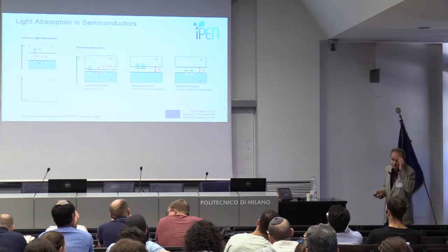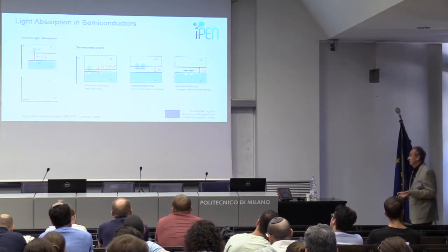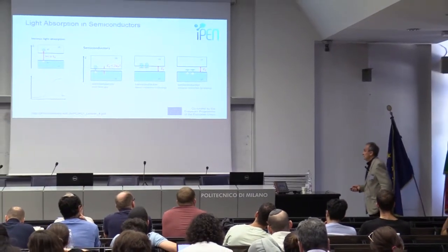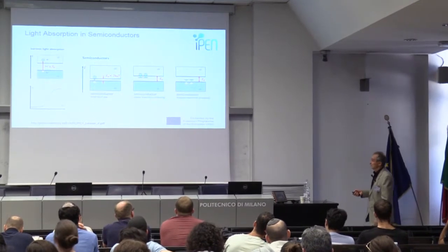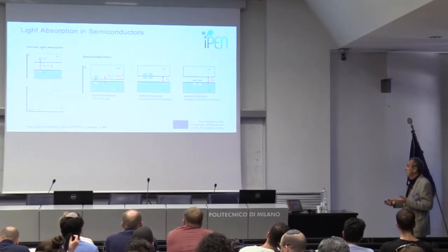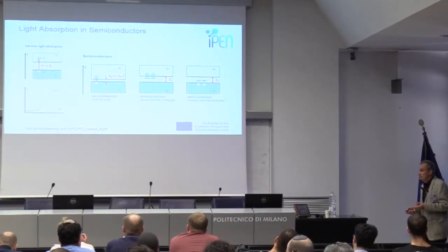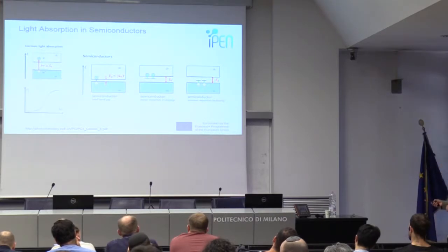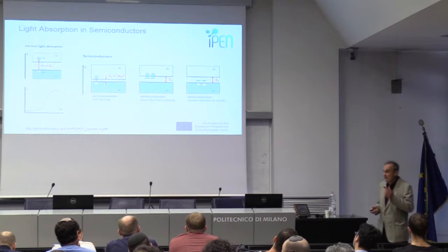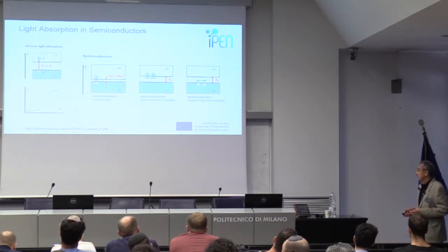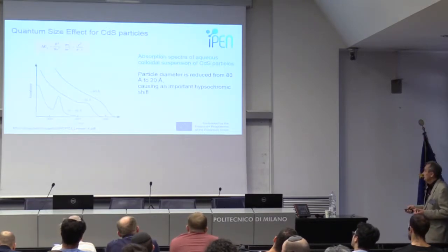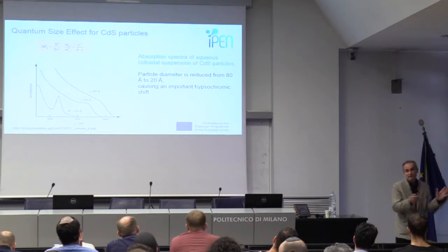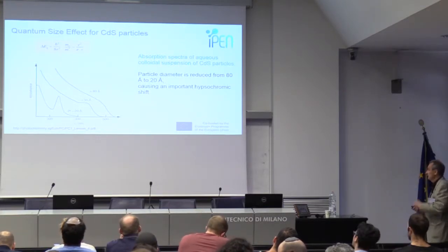Just now, I have promised very short fundamentals. My colleague, Dr. Oswald, gave another talk before lunch about perovskite and so on. Yesterday it was discussed about light absorption in semiconductors. It's really very nice if we have band absorption from the valence band to the conduction band. We can make absorption in very thin films, but it's also possible if we have absorption from donor or acceptor levels, from valence to acceptor. And in this situation, we will of course have nice absorption for engineering with lasers. We should not forget, and I give you this formula for estimating the quantum size effect, the shift of the edge of your semiconductor. It is really simple, but works perfectly.